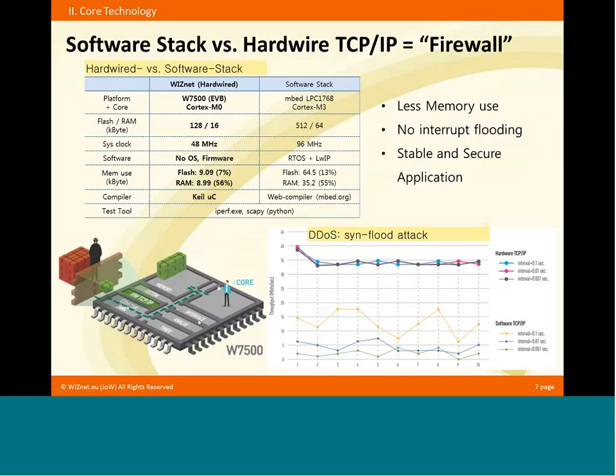What else? We have interfaces: 3 UART, 2 SPI, I2C, analog digital converters. We have a random number generator. We have the direct memory access engine, and we have a lot of GPIO pins. So it's a general purpose 64-pin MCU with a lot of options. And you have to wait just another 4 weeks and everything is published in May. And available in May, so you can place your orders.